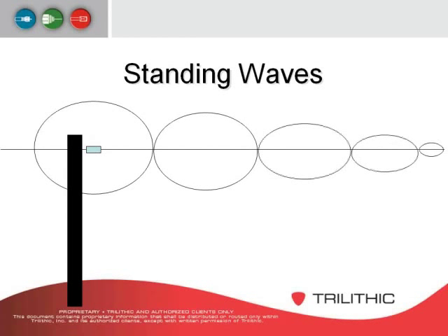You have what's called standing waves. Standing waves is when your signal leak rides the strand, or the shield. So what happens is that the leakage source, like in this example, could be coming from the point right at the utility pole there, but as you can see, the signal will travel down the strand itself. But if you're using your dipole properly, when you're walking the direction of the leak, you should see the leakage intensity level grow.